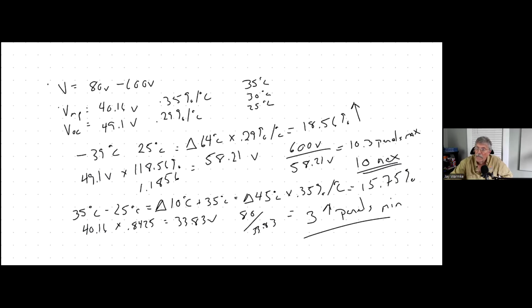If we had decided that our array was, I forget the number, but it was like 10.6 kW, it was 10 something. And these are 400 watt panels. So how many are we needing? It'd be 10,600 divided by 400 gives me 26.5. Well, you can't have part of a panel. So I need to decide, do I want to round up or do I round down? Well, sometimes just how you do this might help determine that.